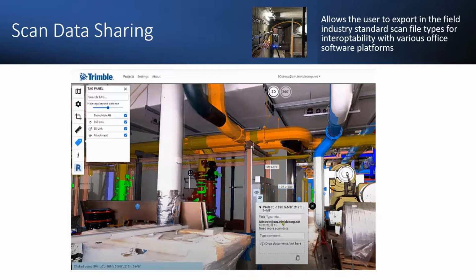Some of the newer sharing platforms we have. This is an example of Trimble Cloud Engine, which is super powerful. Well, there's a desktop version and a web version, but we can overlay, and you'll see, I mean, this is actual scan data, so you see the clarity of it, with BIM models that are overlaid. So we can put in information, we can put in notes, we can put in measurements, tag anything that we need to tag, and then push that to the cloud. So whoever's on the other side, on the review package side, can see that information live, just as we're doing it as well.